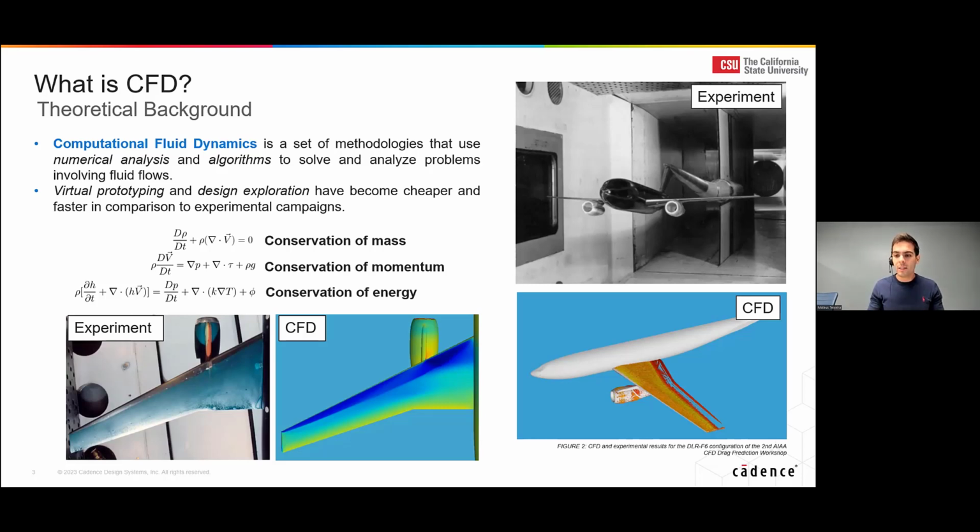On the right-hand side here, I'm also showing another wind tunnel setup, this time for the whole aircraft, including the nacelle. And the goal was to perform a computational fluid dynamic analysis. In this case, I'm showing on the bottom right what we call a large eddy simulation. And what we can obtain for this type of simulation is the prediction of lift, and also in this case, I'm showing the isosurface of vorticity and predict how the flow separates from this aircraft.